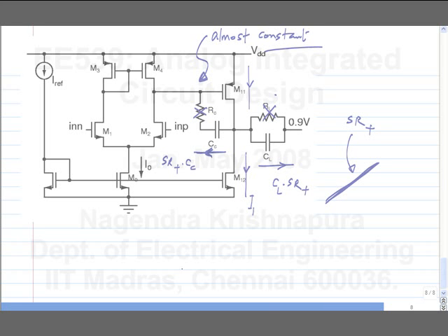Okay. So what limits the slew rate here? Swing of the first stage output, that's it. So first, that is true. That is, the current here is I1 plus this plus this. That much current must be supplied from M11. For that to happen, the input, I said it's almost constant, but it has to go low enough. But let's say the swing at the output of the first stage is low. It is not a big concern.